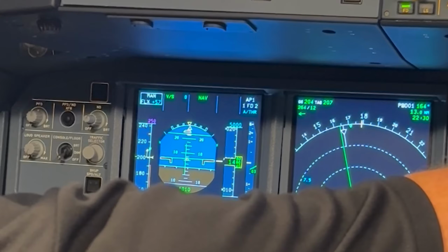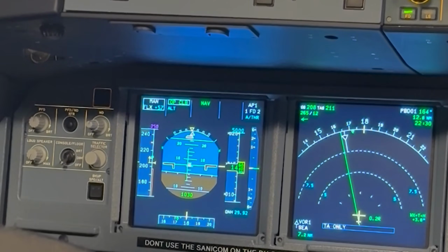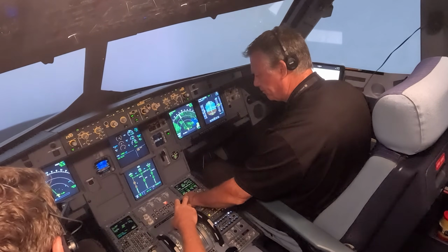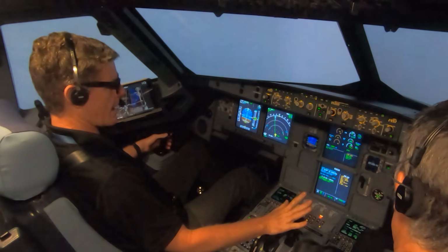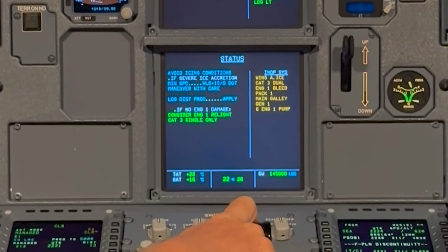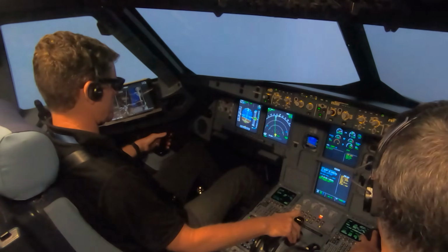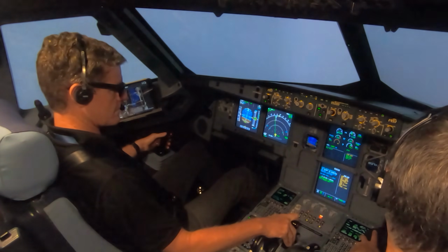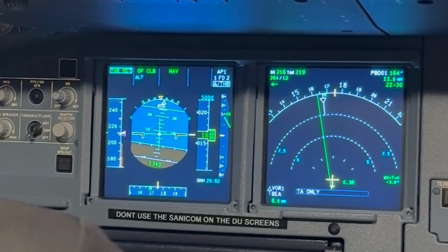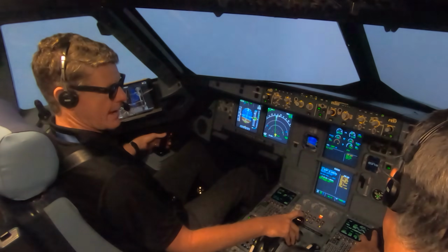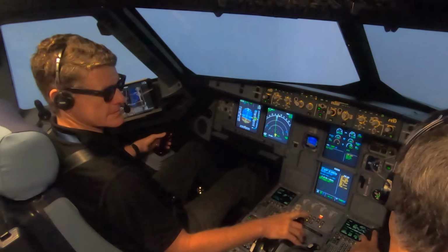Hydraulic page. We've lost the engine-driven pump on number 1 engine. However, all systems are powered. Clear hydraulic. Status. Stop ECAM. Thrust MCT, auto thrust. Okay, the after takeoff flow has been accomplished. I agree. After takeoff checklist.